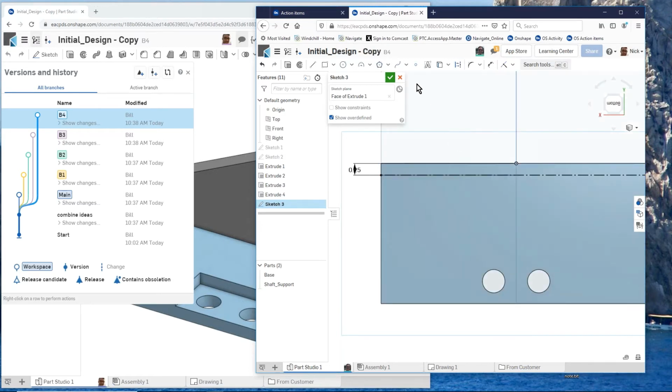Now, one of the things we can do is start placing some points. Wherever I place a point, then I can say I want to put a screw there. So I can say, let's put one right in the middle, right there. I'll put another one maybe over here. So now we have another point. One of the things I'll do is dimension where this point is, because I want to control that. And we'll say, let's make it just an inch over from the side.